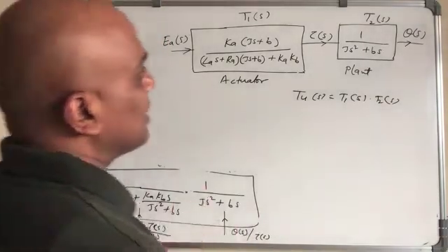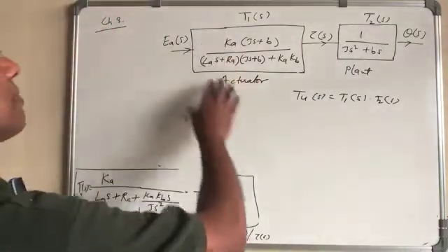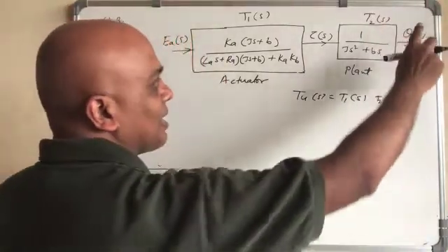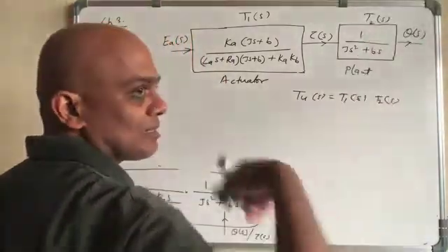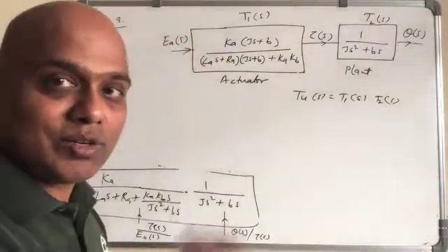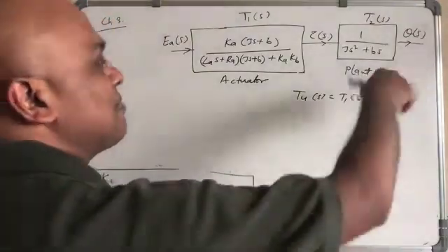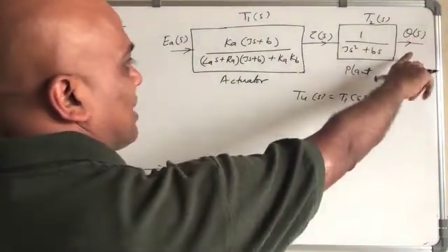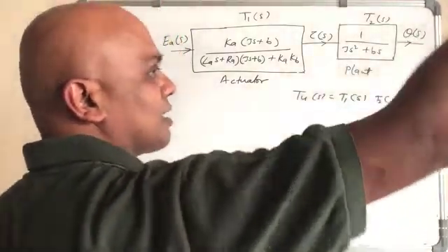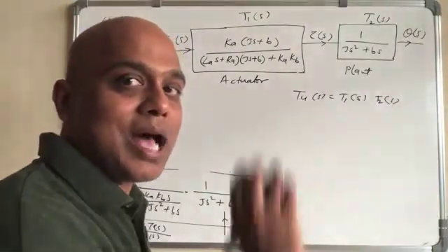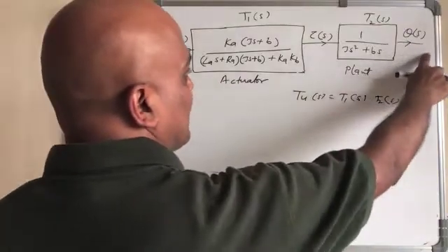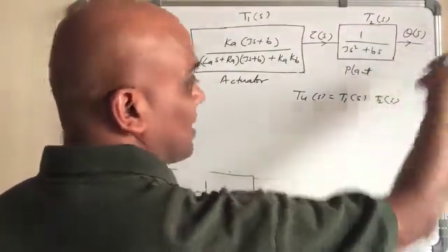Okay. Now there may be other things as well. For example, there may be a gear here, and accordingly the theta may change. So there may be gearing, and depending on the gear ratio, you will have the theta value. For example, if the gear ratio is such that one turn of this one is n turns of the last stage, then there will be a transfer function of n here. Hence, you have to multiply it by n in that case.